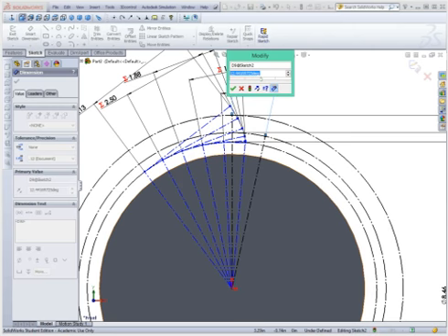But in this case, we have our tooth width, which is 7.85, and our radius, which is 4.5, and again we divide that by 2. So 7.85 divided by 4.5, divided by 2, times 180 over pi gives us 4.997 degrees.